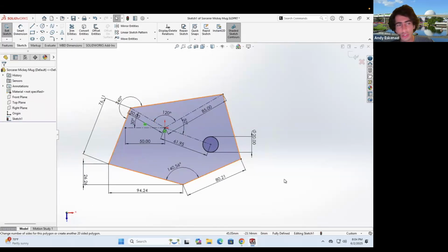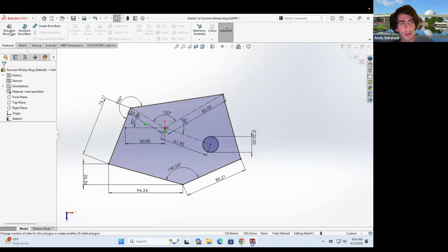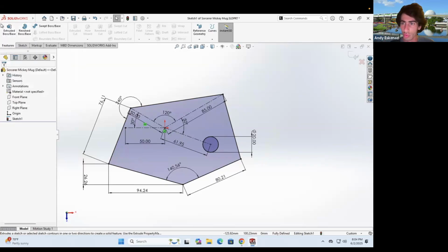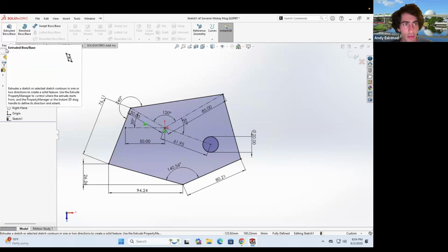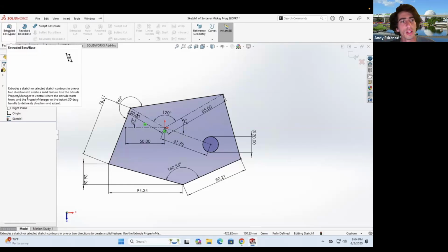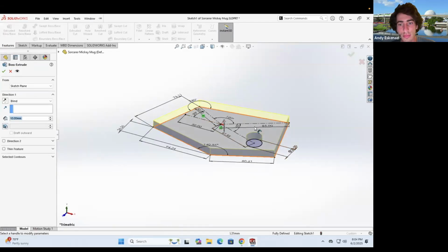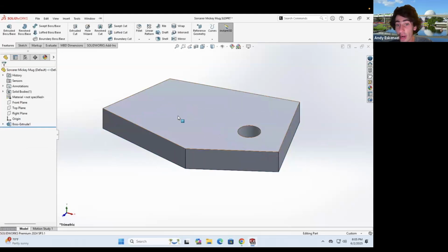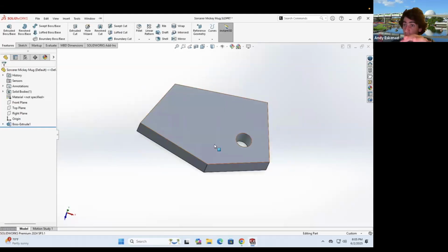So once you reach this point, what you can do is start extruding. And pretty much the focus of today will be about extrusions. We'll be focusing on that while we work on our projects. I will be illustrating how you can be using all of these different tools. So if I go here to extrude, I can give this some volume. I can say that, all right, that's 20. And voila, the solid area that we created before acted as a polygon from where we can give